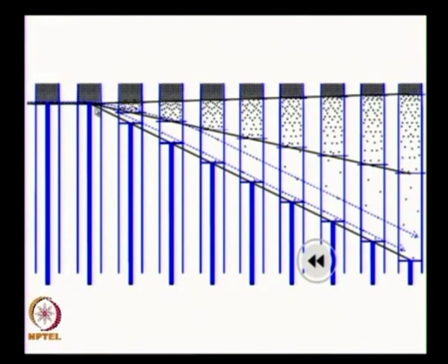What this means is, as it is increasing, I can now say that if my flow is supersonic, you remember this from long back, we said that if there is area change, if the incoming flow is supersonic and the area is increasing, we are going to have higher Mach number. That can also be seen from inside here if we think about the streamlines as stream tube walls. Okay. That is the extra information I wanted to give here in this particular expansion fan example.